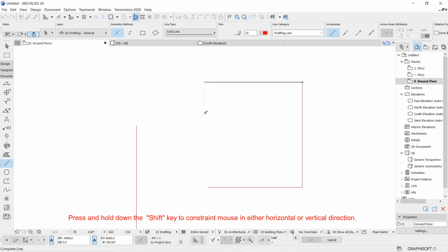So this is known as constraining. You are trying to constrain the mouse in a particular direction, either at the 0 angle or 180. So I'm right now dragging towards the 180. Now make sure I'm holding the shift key down. I have not released the shift key, so it is still pressed. And now I'm just going to keep dragging my mouse down. You can see a perpendicular dotted line getting dropped, and if I touch this particular corner, the end point of that earlier line, you can see exactly R at the bottom of your screen written as 4500 and A as 180 degree.